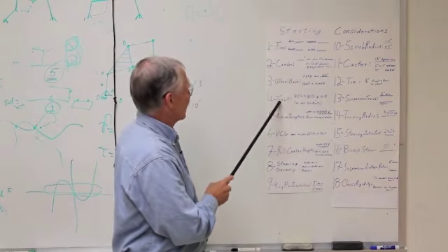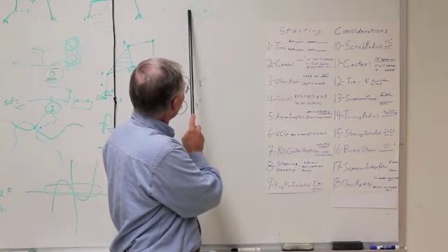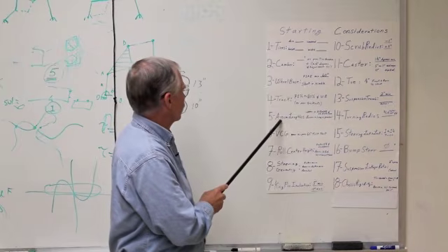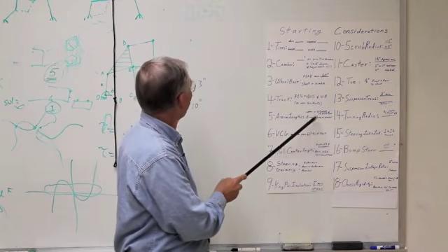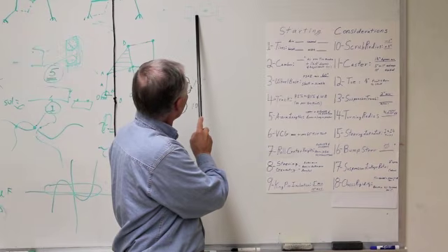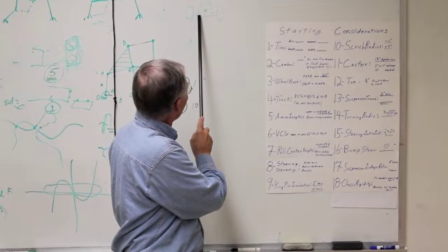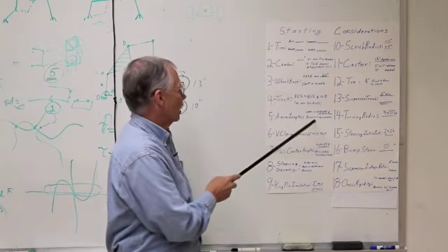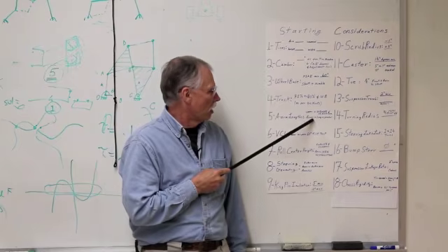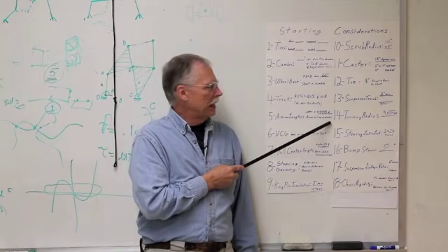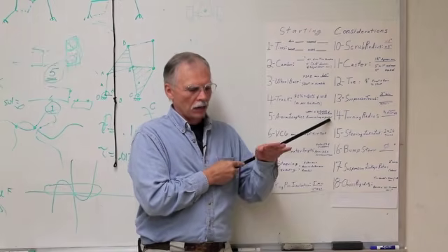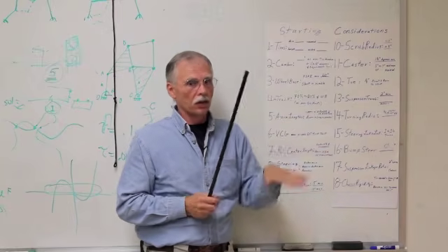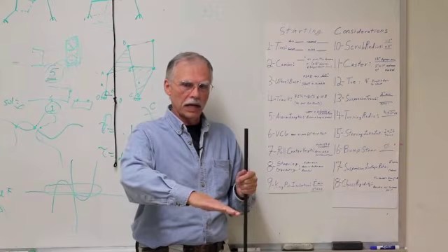Now, once you have established a track dimension, that's the center of the wheels to the center of the wheels, then guess what? Then you can start looking at A-arm lengths. A-arm lengths, that's going to be your mechanical connection from your pivot on the chassis proper out to the upright, which is supporting the wheel. Here's the general rule of thumb on that. The longer the lower A-arm, the easier it is to get rising camber geometry that you'll need when the car banks over, rolls over in the turn slightly, and you want to keep that contact patch flat on the ground.